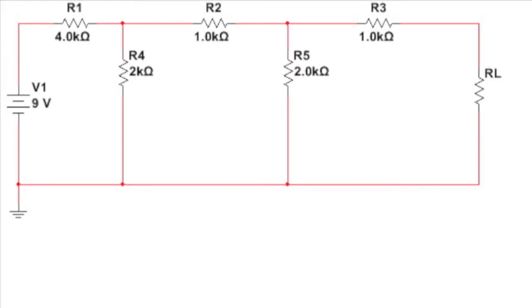It turns out that there's a 2 milliamp current limiter in my DAC system, and there was just no way with the original circuit I had I was going to be able to get the appropriate voltages. This is why I added resistance into the circuit in order to drive the current needed down. Now, this is really probably the biggest thing I learned during this whole project, so I wanted to make sure this is a really key point to point out.